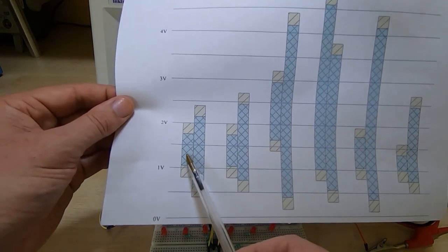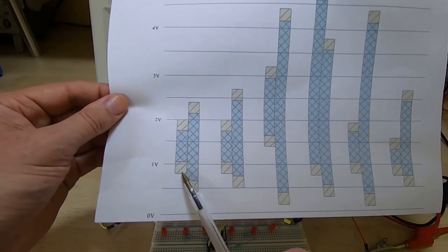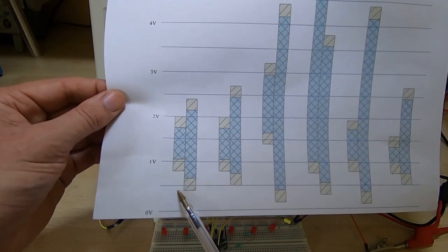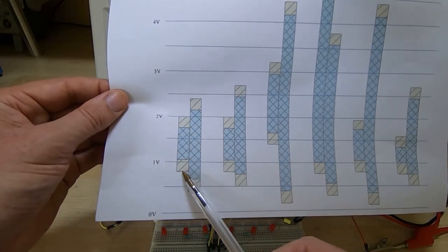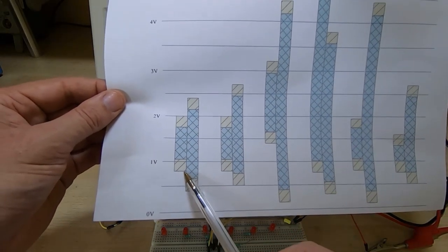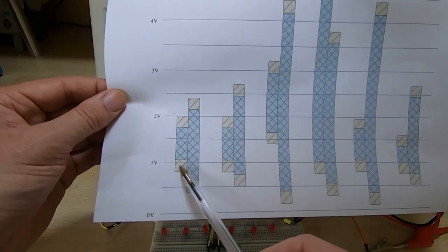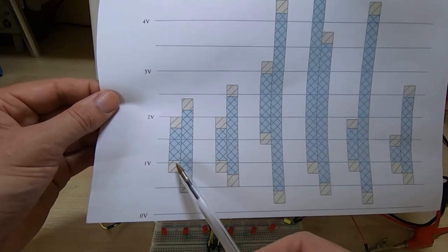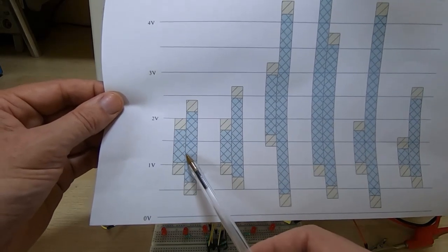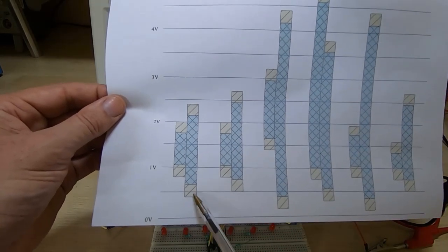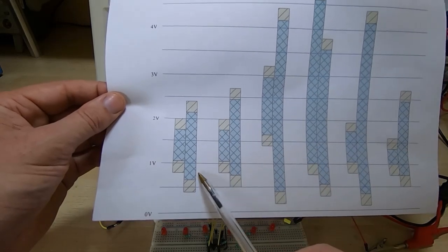So in other words, with a standard TTL device you'll get an input range that's accepted as being greater than 2 volts for high, less than 0.8 volts for low, and the area in the middle is an area that shouldn't really be used, and you should aim to get your signals through these areas as quickly as possible. The right hand bar is the output values.